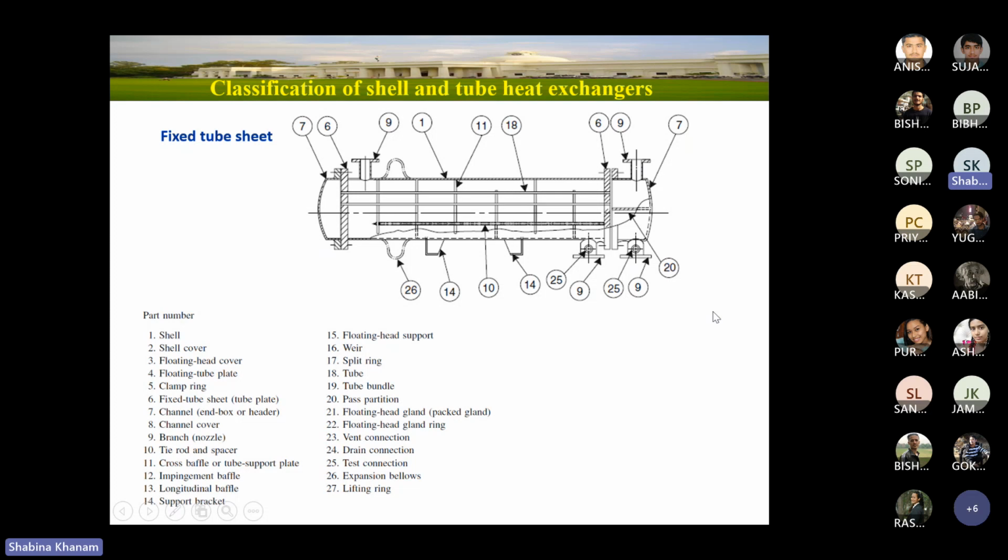Okay, now as far as tube passes are concerned, the tube pass basically tells you how many times the fluid will enter in tubes. Okay, please keep in mind how many times the fluid enters in tubes. If you consider this schematic, here I am having 1 2 pass.